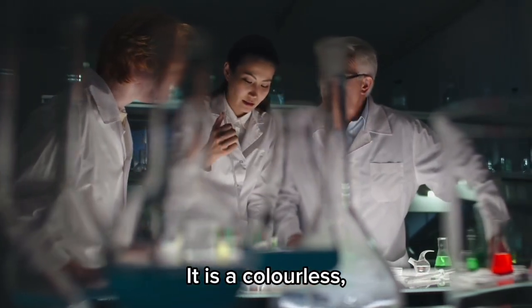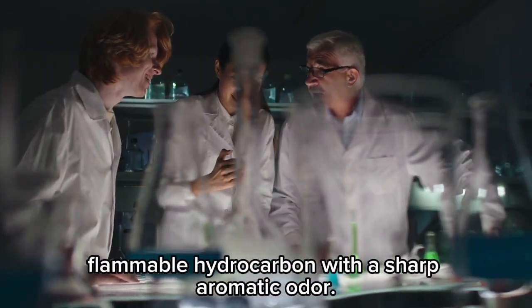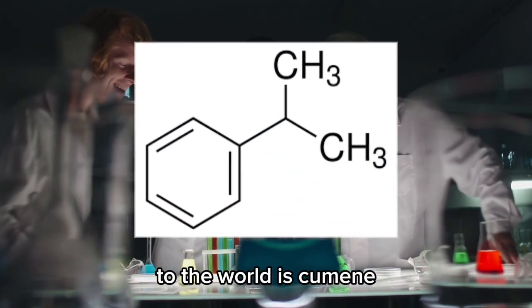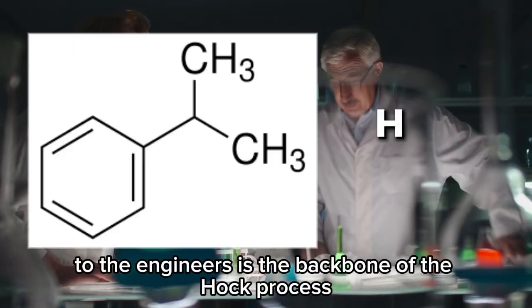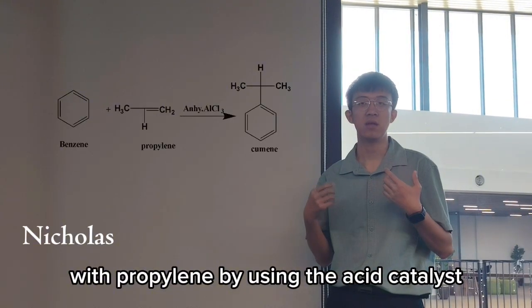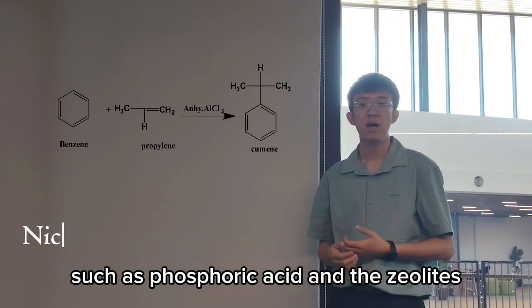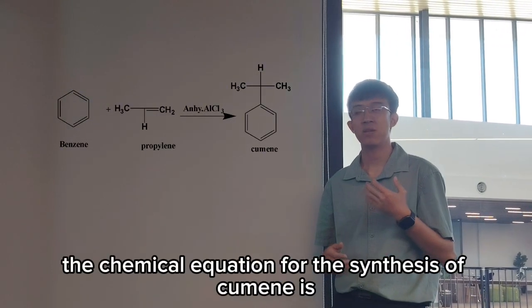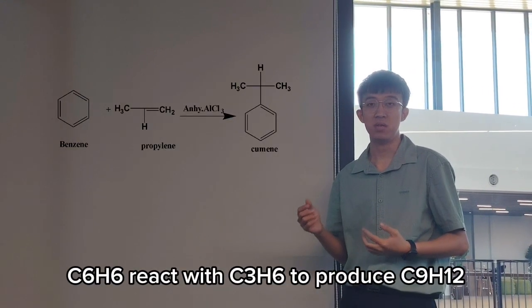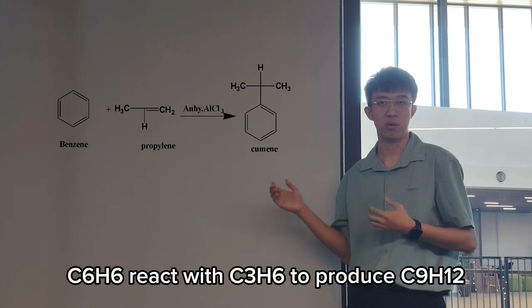It is a colorless, flammable hydrocarbon with a sharp aromatic odor. To the world, it is cumene. To the engineers, it is the backbone of the phenol process. Cumene is synthesized through the alkylation of benzene with propylene by using acid catalysts such as phosphoric acid and zeolite. The chemical equation for the synthesis of cumene is C6H6 reacts with C3H6 to produce C9H12.